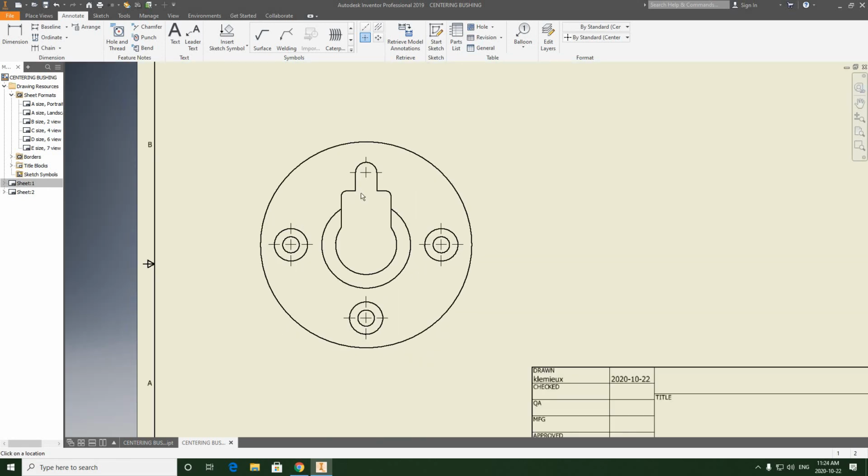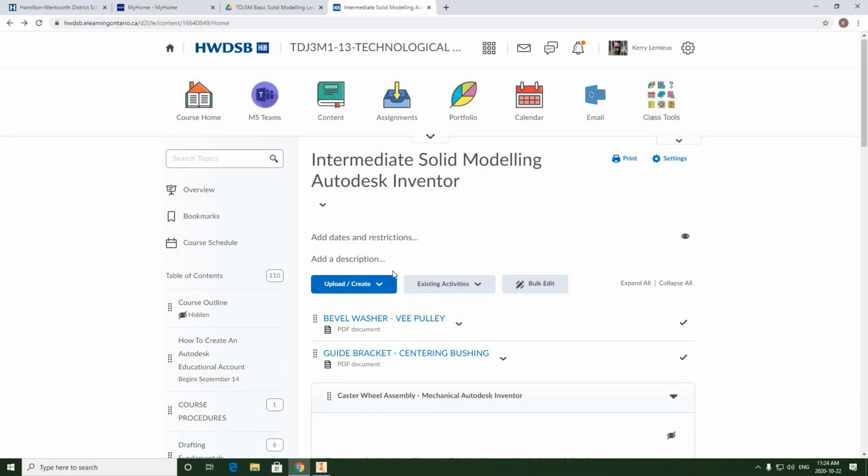And we're also going to be adding a center mark here, all right, to be able to pass through horizontally the middle. Now this center line here, it's going to be overwritten in a moment. When I add the section view, it's going to be covered with a thicker, larger line that runs from top to bottom. And that's what we're seeing here.